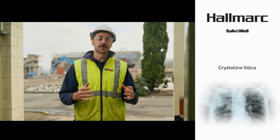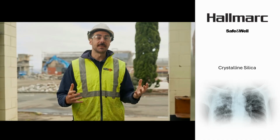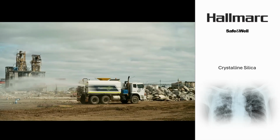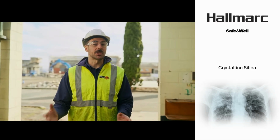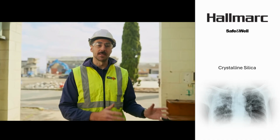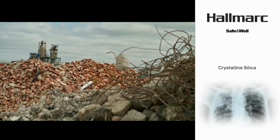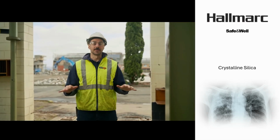Dust curtains can be used to direct airflow towards an air scrubber, or to contain dust within a work area. To be effective, dust curtains should be creating a seal. Dust curtains need to be paired with other controls like dust extraction or dust suppression systems. To keep dust from becoming airborne from areas like stockpiles, haul roads or conveyors, polymer sprayers can be used to form a film over that material.